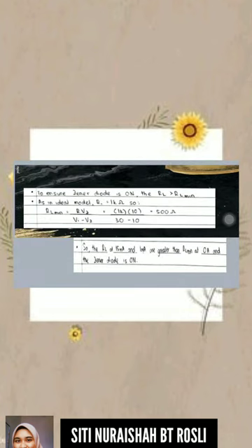As explained before, to ensure the Zener diode is on, the RL must be greater than RL minimum. In the ideal model, we can find the value of RL minimum by using the formula R multiplied by Vz divided by Vin minus Vz, and we get the answer of 500 ohm.